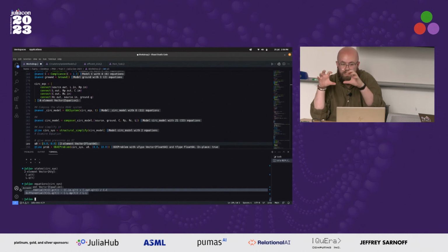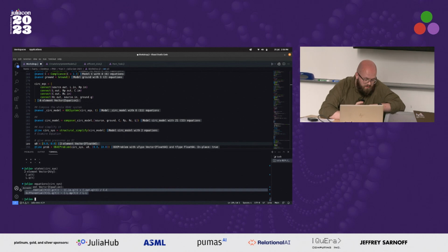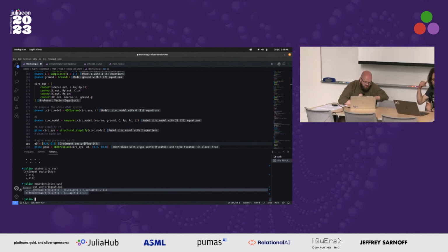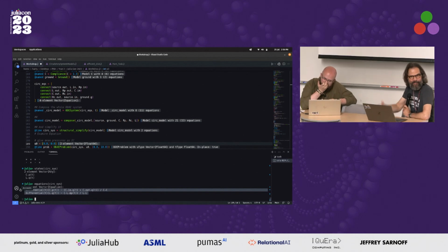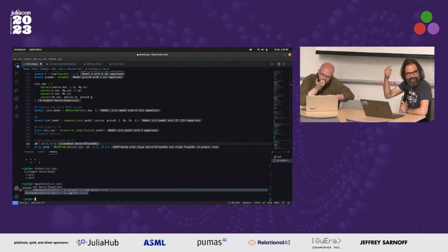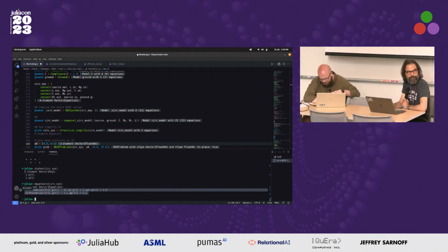So the whole system will have that constraint applied to it at each time step. It may be that I usually stick to the ODE system, which technically is the wrong definition for that second system we had with one ODE and one algebraic constraint. But the solvers in DifferentialEquations.jl are usually clever enough to sort that out for you.